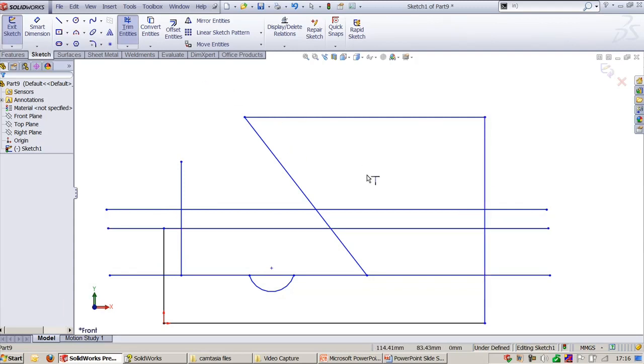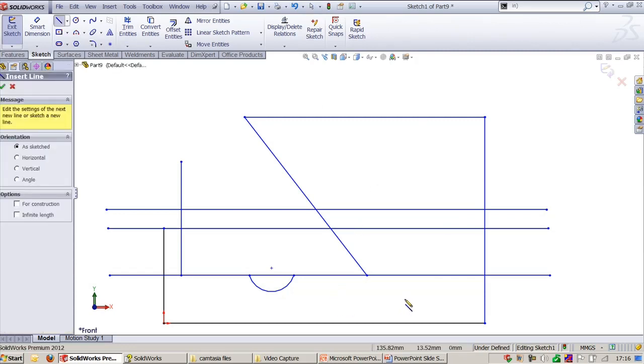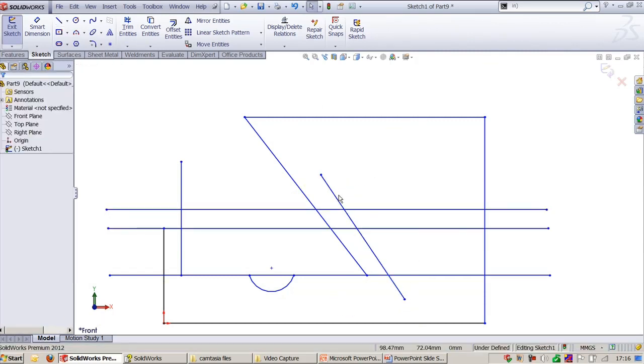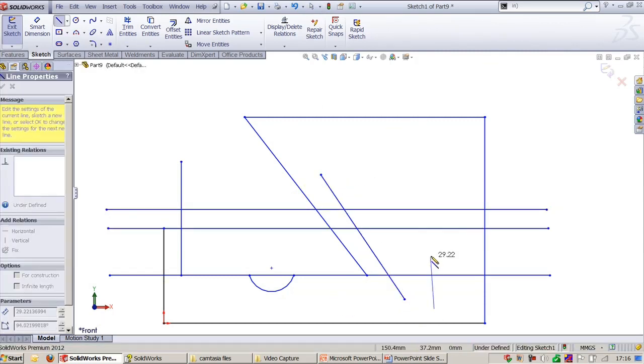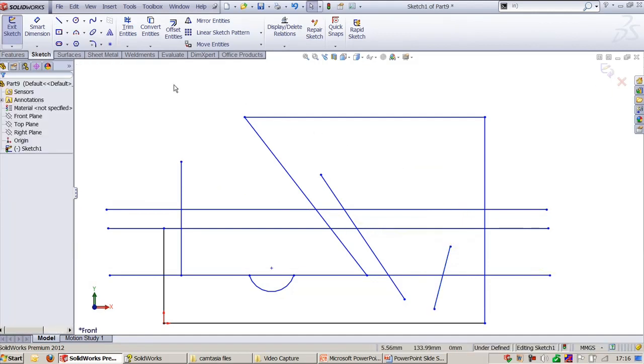And when you create any line segment, say I have a line segment like this and have a line segment up to here, and when I go to the extend command, it will give you an option how much you can extend, up to which boundary. If I say this, I have to extend up to where, I can say up to here I can extend. So this is how we can do trim and extend in SolidWorks.